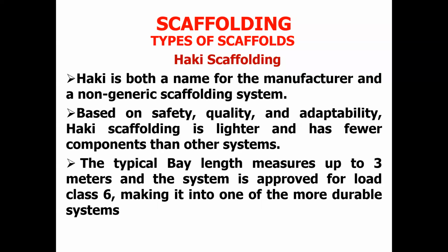When you want to propose a scaffold for a particular project, you need to look at a lot of things. You even need to look at what load this scaffolding is going to support. When you talk about the load, you talk about the load of the worker, the artisan, or whoever is going to stand on that scaffolding to do any work. And then you look at what kind of equipment they are using for that work, what kind of tools they use at that height where they are working. You also need to look at what kind of building elements you can temporarily support on the scaffold before fixing them on any part of the building that you're working on.